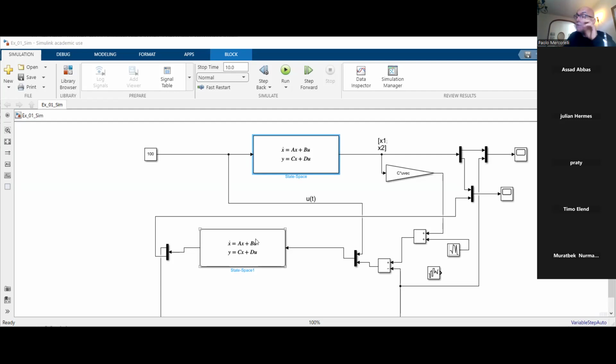It's an assumption. I don't know if you remember the calculation of last week. I assume that I know perfectly the model, or at least I know perfectly the system, and the model reflects exactly the system. In the Kalman filter, if this is not valid, we have some problems. I told you last time. And this problem could be, I don't want to say totally solved, but could be managed by the Kalman filter.